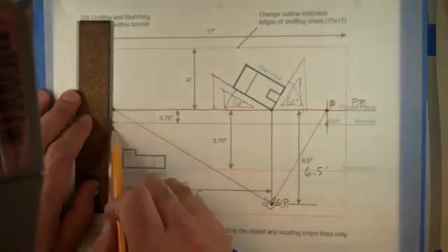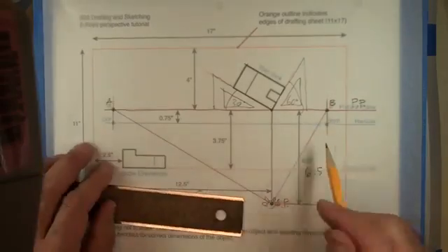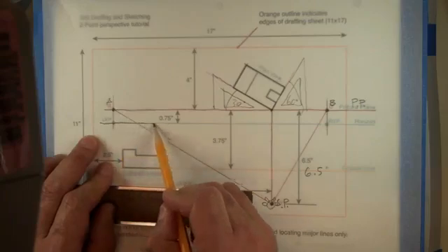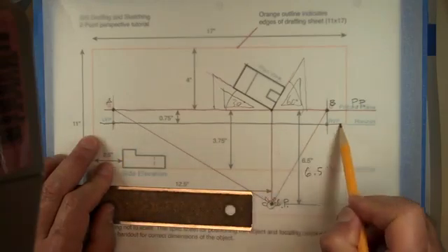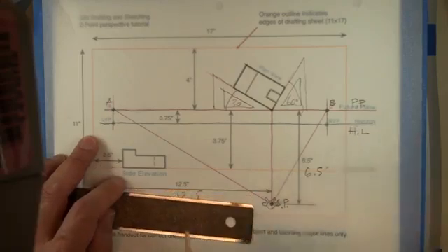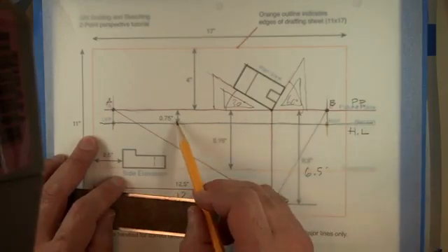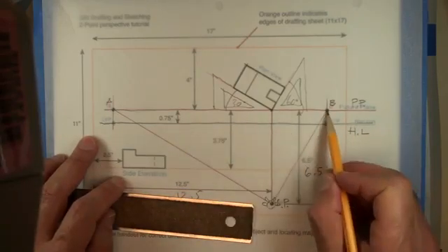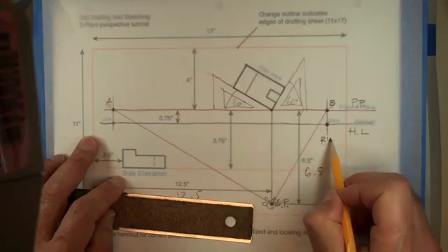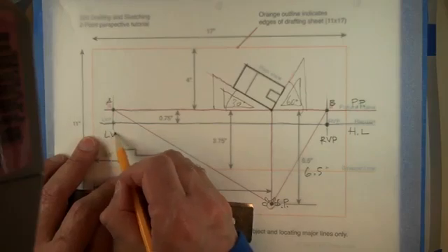And they come down vertically, and when they hit the horizon line, which will be, again, in this case, we pick it. We just decide, okay, the horizon line is pretty high. In this case it's 3/4 of an inch. When it hits that line, that's your vanishing point. Okay, so that's your right vanishing point, and this is my left vanishing point.